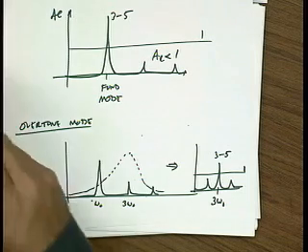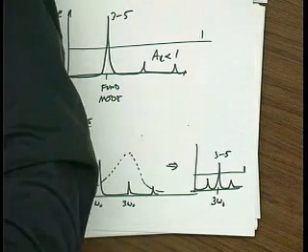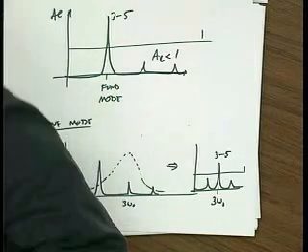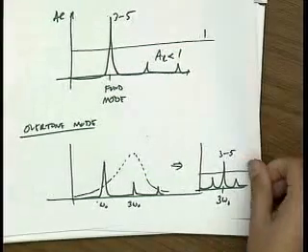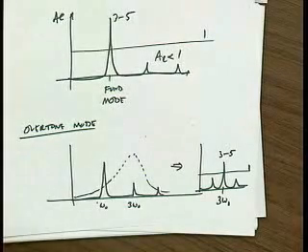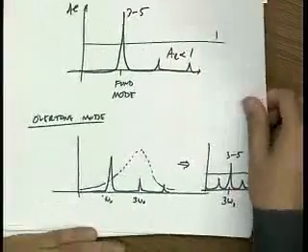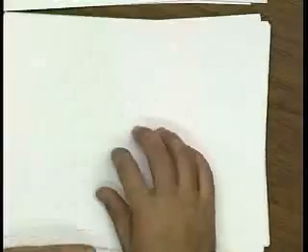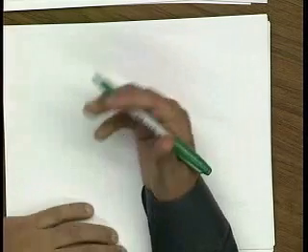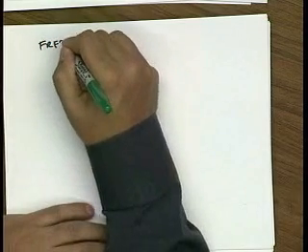now another fundamental question comes to mind: you have these crystal oscillators, they're very nice, but their frequency doesn't go beyond, let's say, a couple hundred megahertz. So one option is you go use MEMS resonators, right? But MEMS is an add-on. It actually doesn't really exist today. In a year or maybe a couple years, you'll have the option of maybe using MEMS resonators with a standard process. But again, it's going to be much more expensive. So if you want a low-cost solution, you need some way to synthesize a higher frequency.